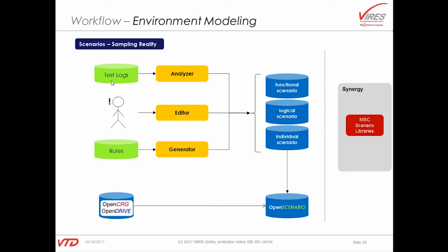And we also find now what is called replay to simulation. We often find the situation that people have their own test logs from actual test rides and want to see this information in the simulation. And this is where we then take an analyzer, for example, which just takes all the CAN messages recorded on a vehicle and then generates from this the dynamic behavior of entities within a 3D environment.